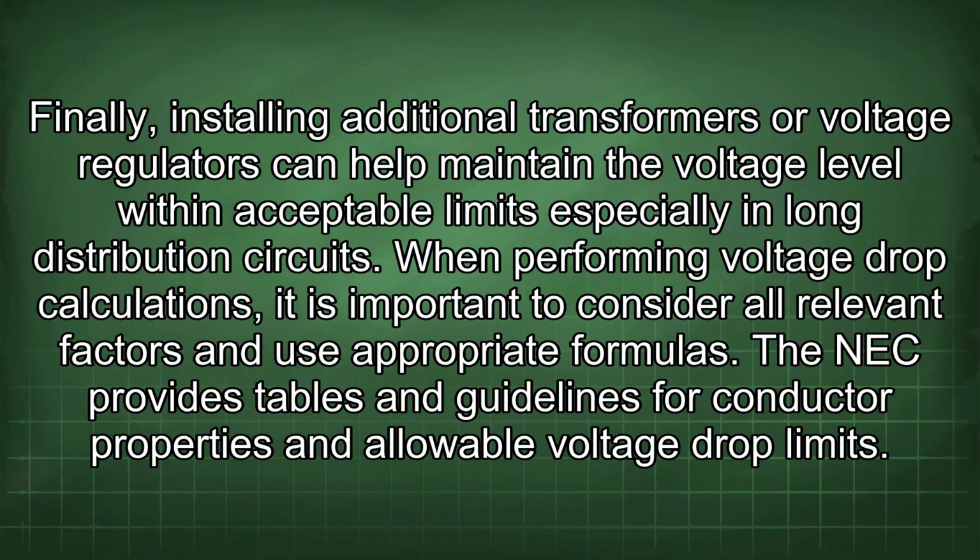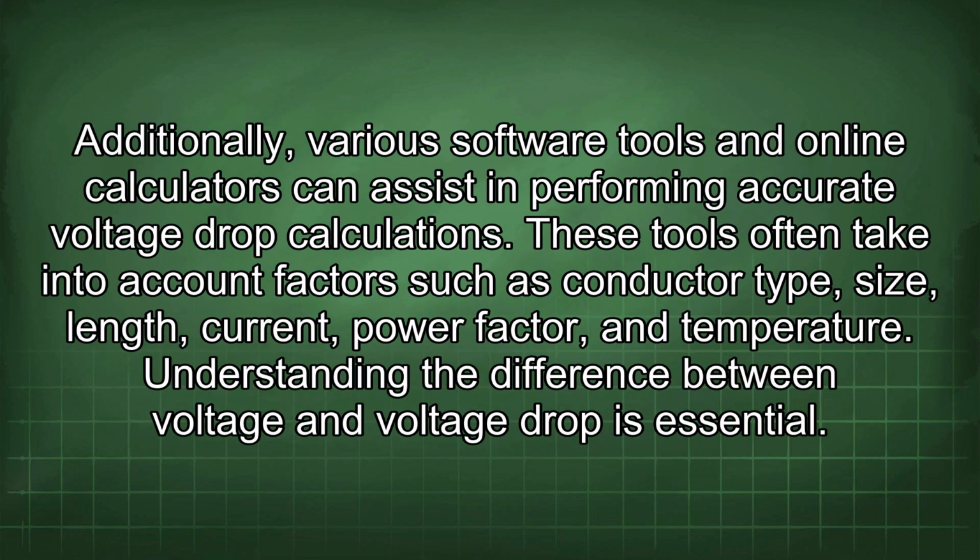When performing voltage drop calculations, it is important to consider all relevant factors and use appropriate formulas. The NEC provides tables and guidelines for conductor properties and allowable voltage drop limits. Additionally, various software tools and online calculators can assist in performing accurate voltage drop calculations. These tools often take into account factors such as conductor type, size, length, current, power factor, and temperature.